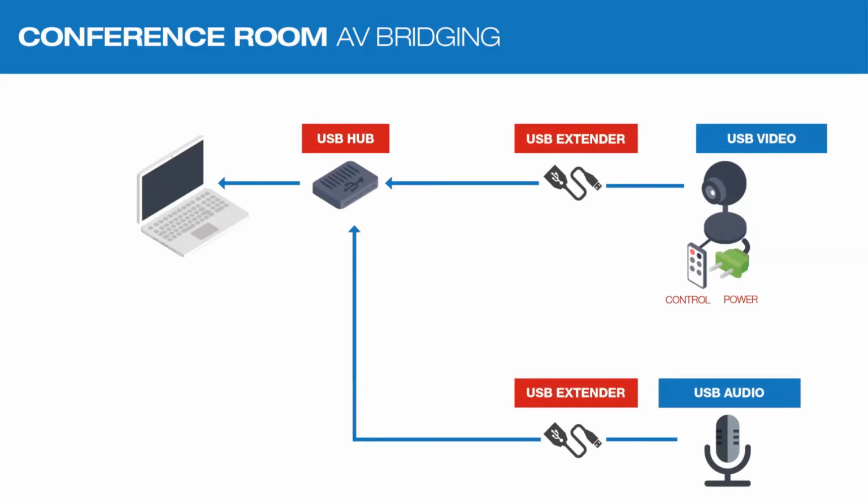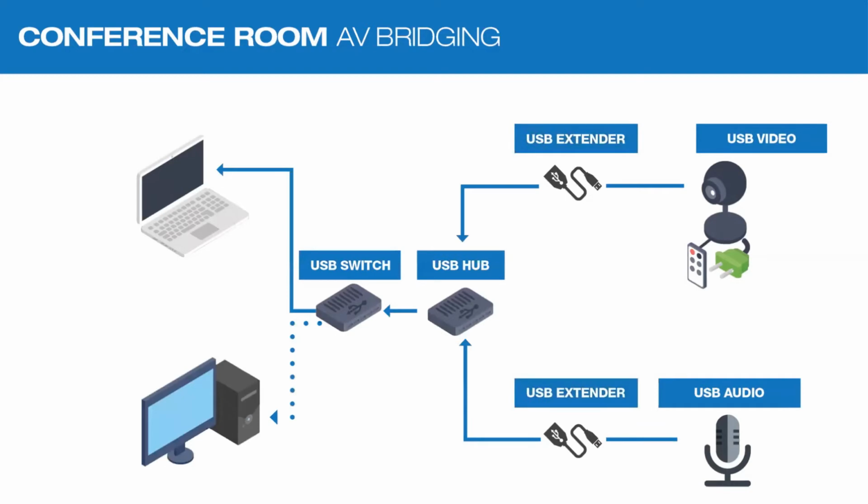If we need two endpoints, so we've got your rack mount PC and you bring your own device, you'll need to add a USB switch in there as well. Very often installers will add cheap plastic switches, hubs, and extenders, and the whole system really depends on what's often the cheapest part. USB wasn't designed to be used in this way, and it will probably work sometimes, but it's really not the most reliable solution that can be presented.